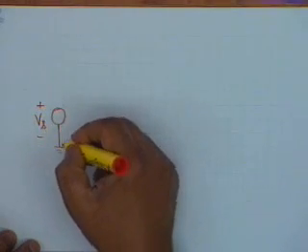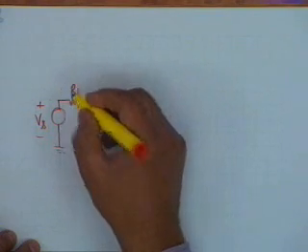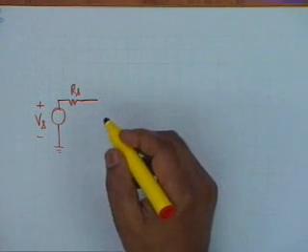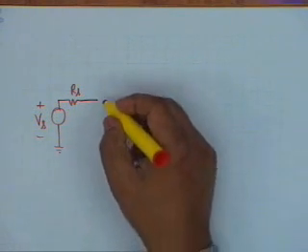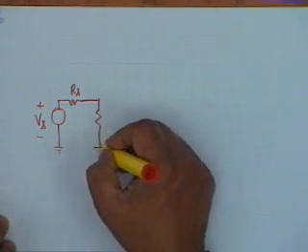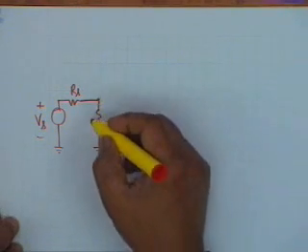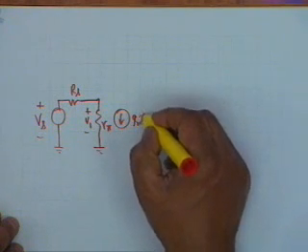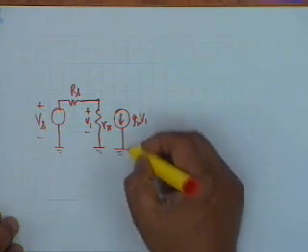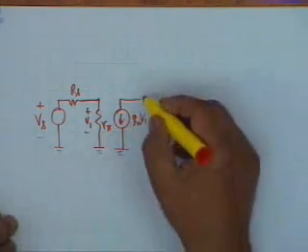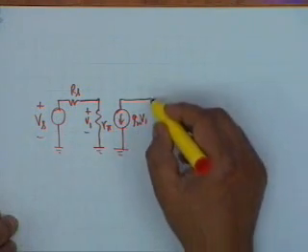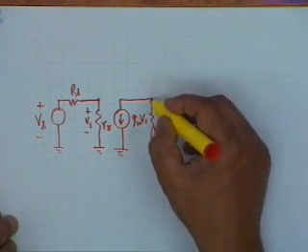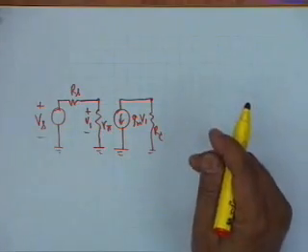Vs, then you have Rs. We have ignored R1 parallel R2, and therefore it is simply R pi. R pi, and if we call this voltage V1, then the output of the collector is gm V1, and its load is, there are two loads, one is R sub C and the other is R pi of the next stage.